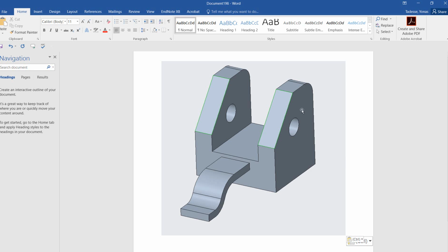Okay, let's see how we can create the solid model of this object shown. The first thing to do is create a strategy to make this composite 3D 2.5 model. As you can see here, this object can be made by a U shape, a simple extrusion, hole cutout, and some fillets, as well as this portion.